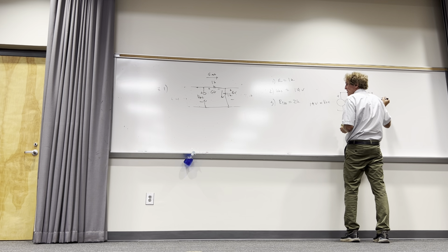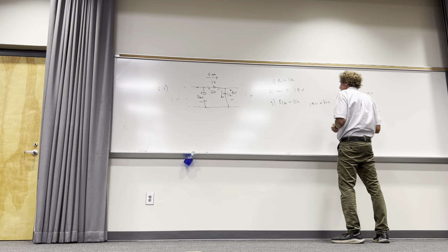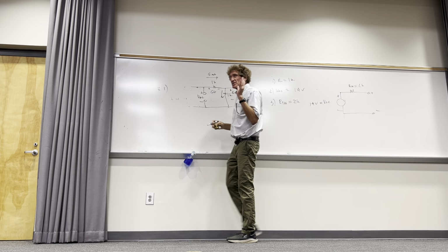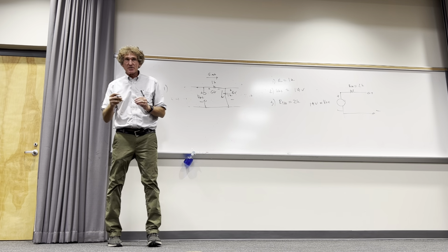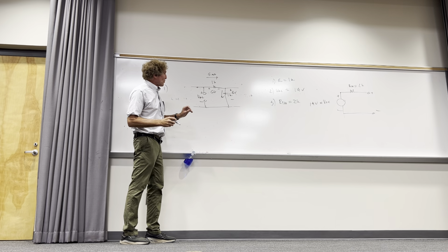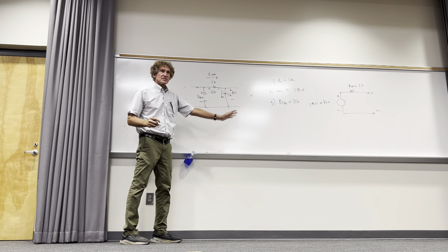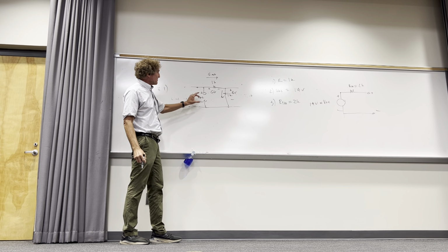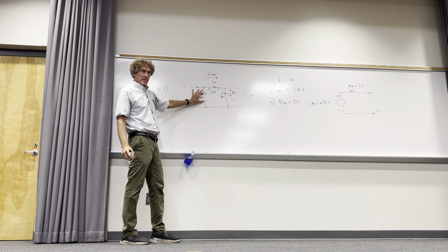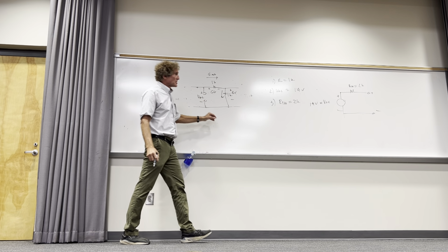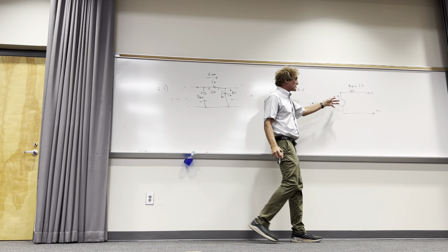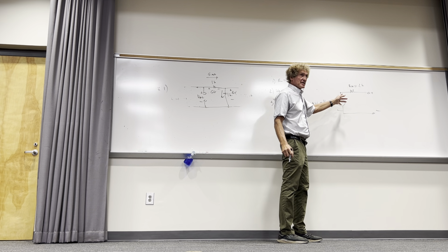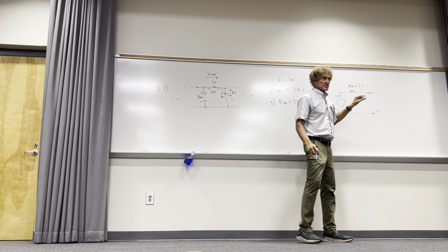This is where I actually want the current. Now that is the equivalent circuit. I want you to hear me now. This is why it's so nice to do it this way. At this point, I've taken that entire mess and I said, regardless of the value of the resistor here, the entire circuit that would cause that voltage can be reduced to simply a single voltage source and a single resistance.